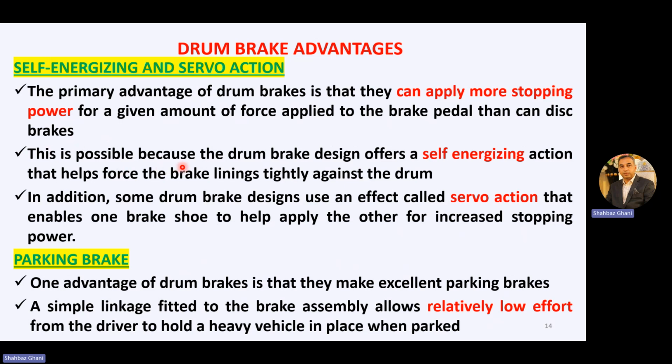This is possible because the drum brake's design offers a self-energizing action that helps force the brake lining tightly against the drum. In addition, some drum brake designs use an effect called servo action that enables one brake shoe to help apply the other for increased stopping power.